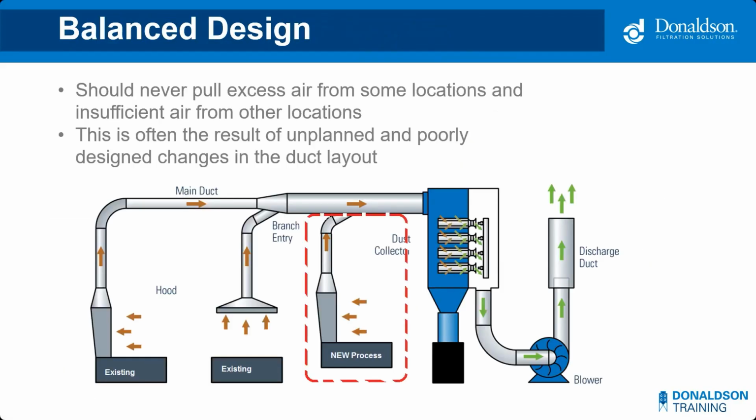As I mentioned earlier, having an unbalanced system is something that can go wrong with duct design. When customers add new equipment to an existing system, they often don't consider the impact it has on other existing equipment. In most cases, existing equipment wasn't modified to accommodate the additional airflow or static unless it becomes unbalanced. Luckily, if you know a school is going to be expanding their process, there are ways to design future lines into the system so they don't have to sacrifice performance.